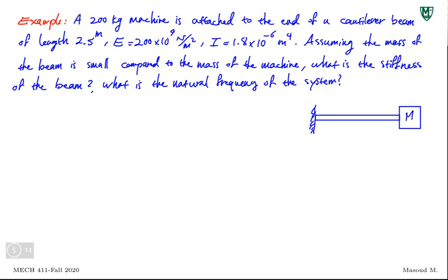And they want to know the natural frequency, because we'll see later on it really is important. When you design something, you stay away from natural frequency 90% of the time, to make sure that you don't have huge oscillations. We'll talk about it when we talk about forced vibrations.